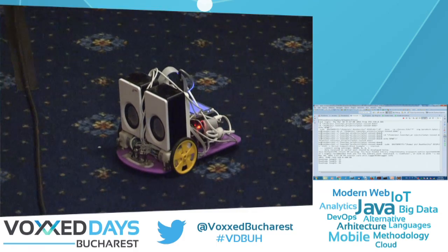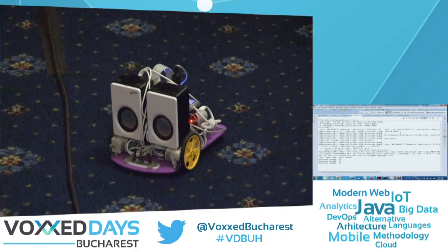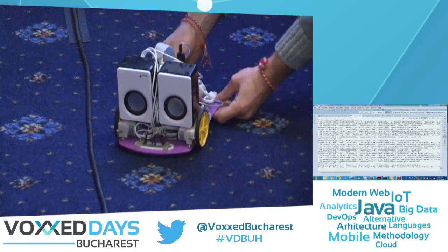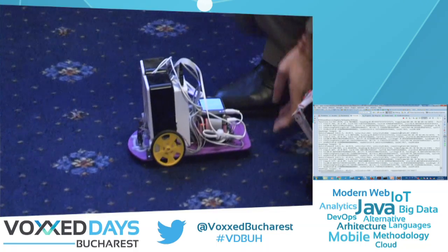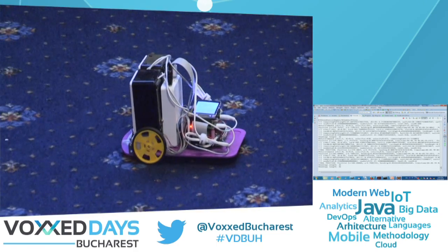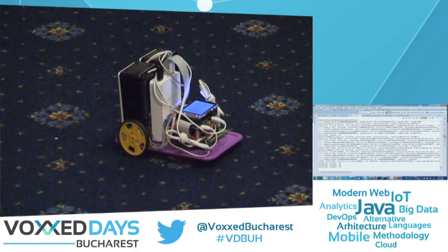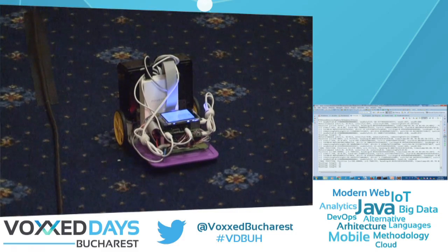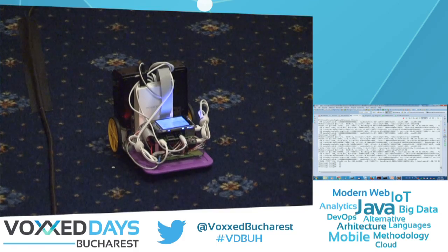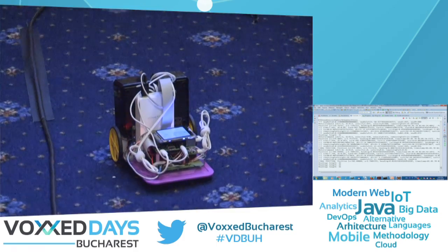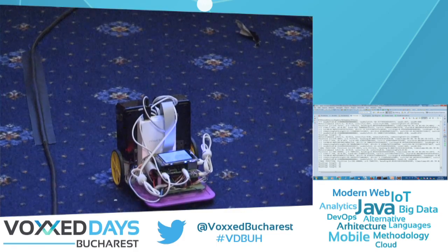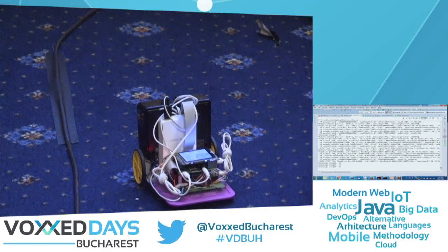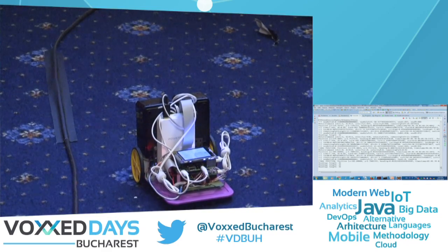Next I started from here, going straight to A. In this demo, we see it goes slightly in the other direction, but it compensates. It's adaptive. You can see here it's just 0.02 millimeters, according to the encoder's readings, divergence from the straight line, from the target direction. And there are 3 millimeters in the Y in the end position, for 40 centimeters.